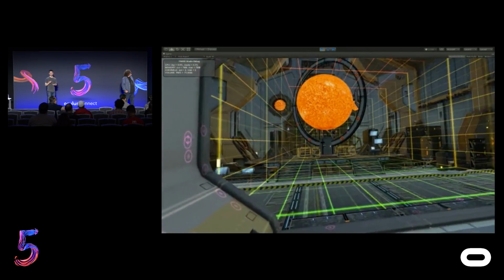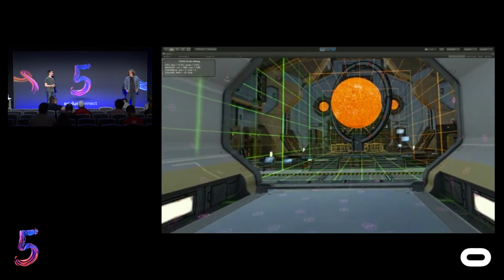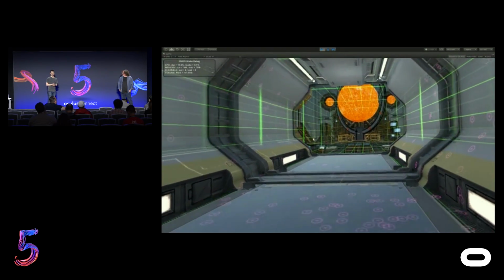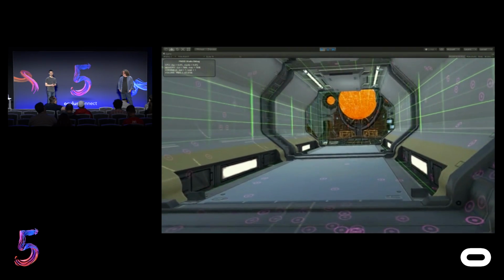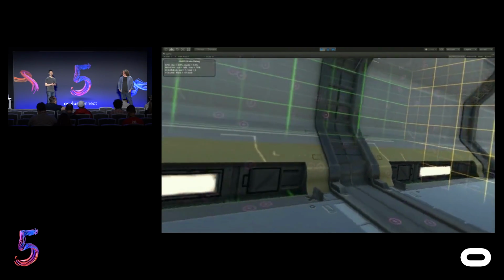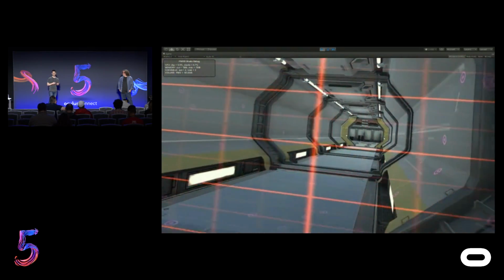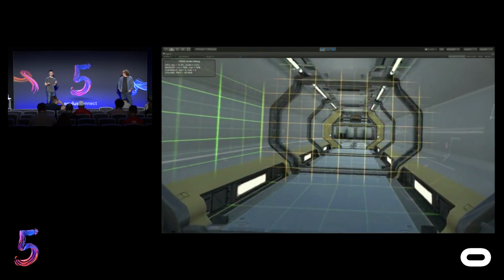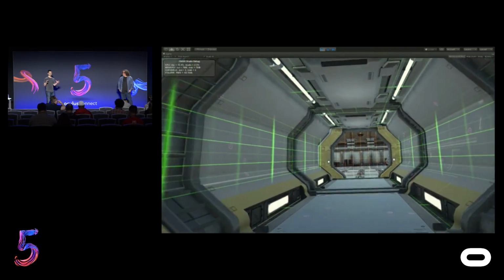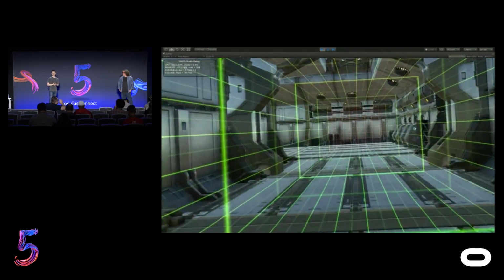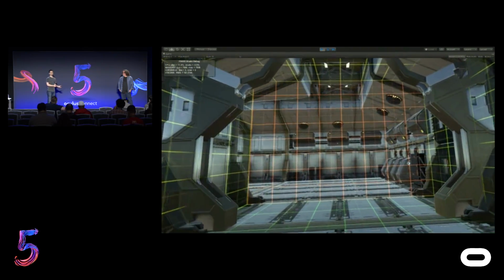So this is a feature. It's available now. It's in the Audio SDK. It works with Unity. We've also got it available for UE4 as well. And it's going to draw this overlay in-engine so you can see what's happening in real time. And there's some parameters you can use to dial it in. So how many rays it's casting and how fast the smoothing is. And the performance of the actual raycasting and stuff like that is really minimal. And it just leverages the game engine's raycaster.